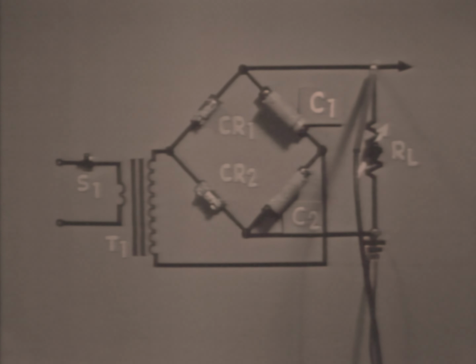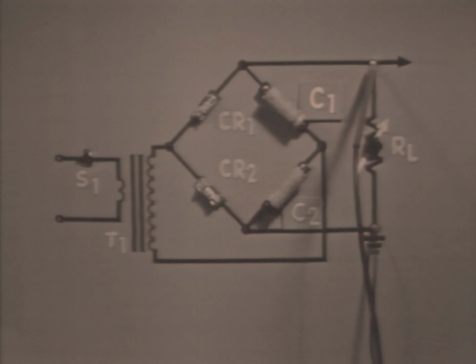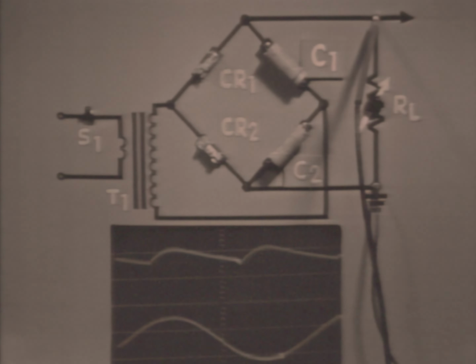Now, let's determine the effects that the load has on the voltage doubler. Now, the effect of a load change on the output voltage can be demonstrated quite effectively using this circuit. The load resistance, represented by the variable resistor, is now at maximum resistance. Therefore, output voltage is maximum for this resistance, and output current would be minimum.